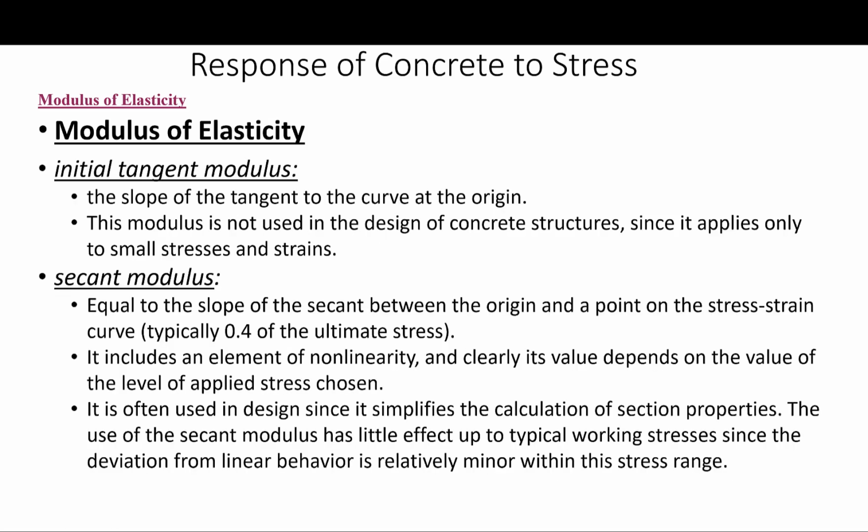So the secant modulus is, as we said, often used in design since it simplifies the calculation of the section properties. The use of the secant modulus has little effect up to the typical working stresses, since the deviation from linear behavior is relatively minor within the stress range, okay?